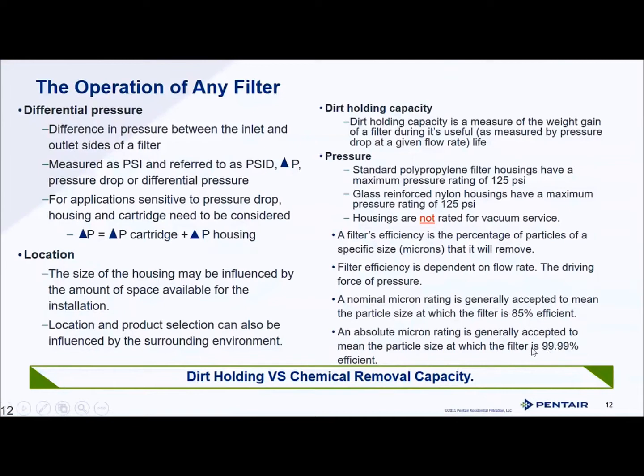And this is where we're removing 99.99%. The reason this is there is because of bypass at the top and bottom of the filter due to pressure or water hammer in a system causing blow by instantaneously. So that's the reason why this isn't 100% on an absolute micron rated filter: you do have those minor technical issues there to resolve.